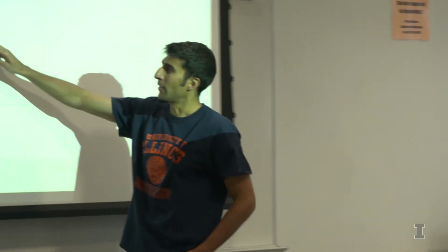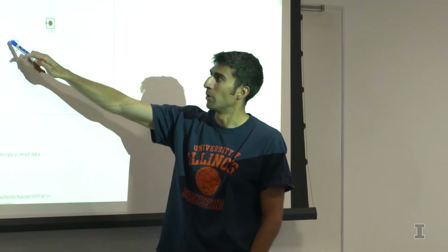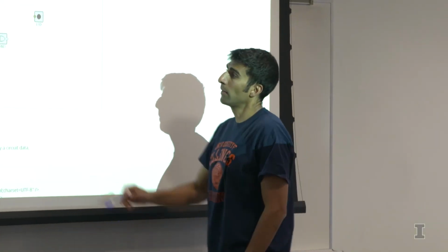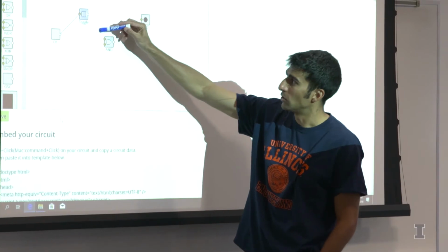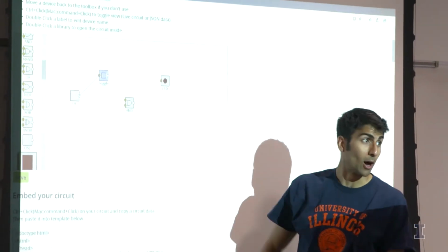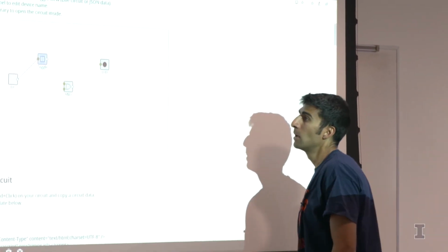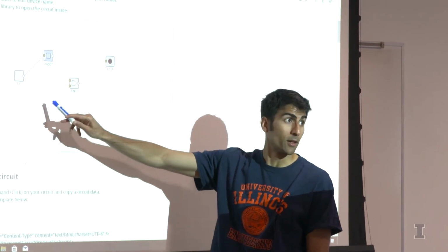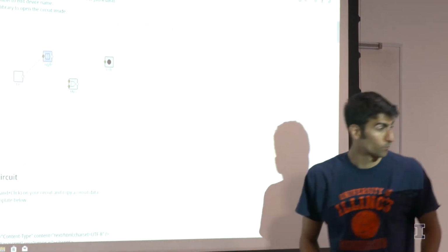If we look at the AND gate, there's two inputs, two yellow dots, and one output, one white dot. That means this is going to be a function that's mapping two variable input to a one variable output, right? So we're going to need to bring in another toggle because that's going to be another input variable. So let's bring in a second toggle.